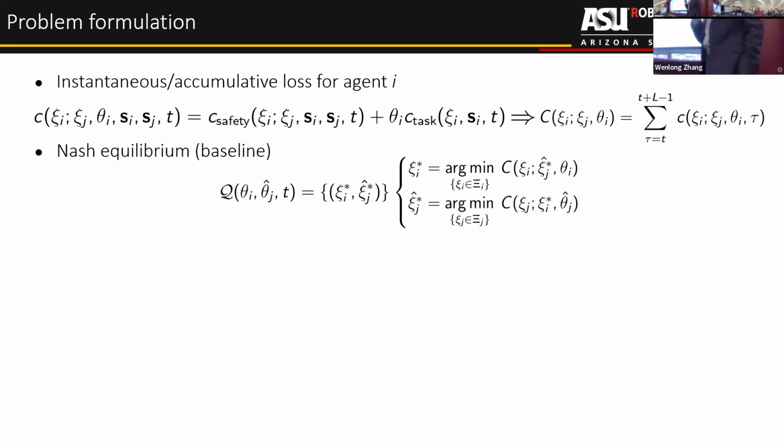The baseline is you assume the other vehicle will just minimize their own cost function, assuming they know what you will do, right? For example, if we run that in a temporal fashion, that is to say, if I give an optimal action here, then we assume the other vehicle knows what I'm doing, right? Or we assume you have direct observation of my control input.